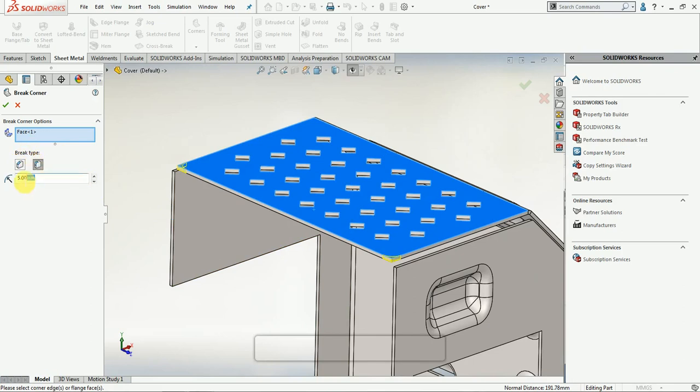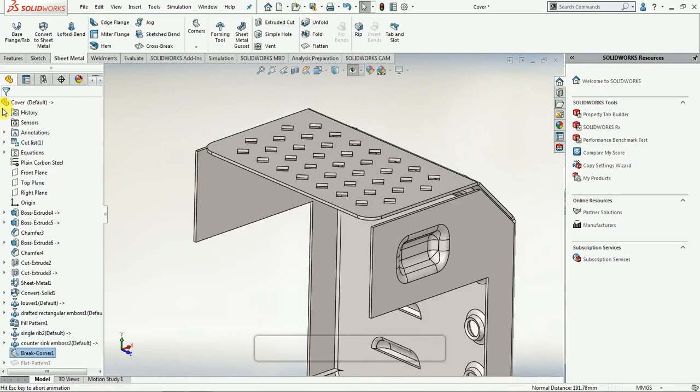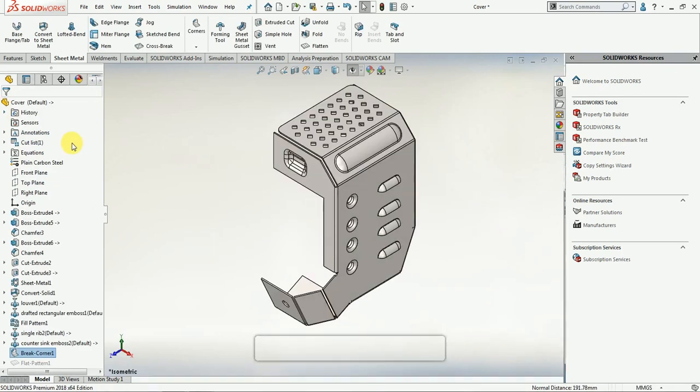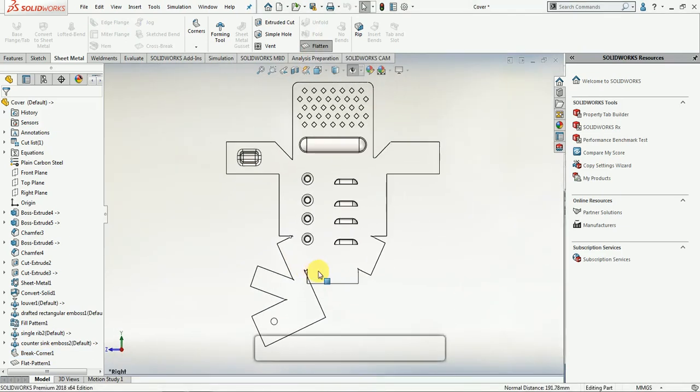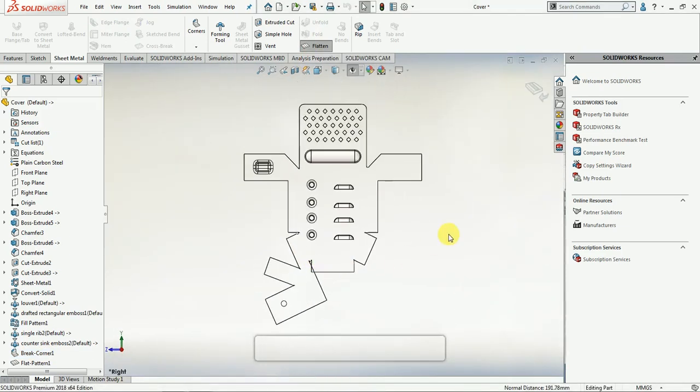I am just keeping my fillet at 8.5 mm radius on my edges. So within a matter of seconds I can create a solid body, convert that solid body into a sheet metal and calculate the blank development area.